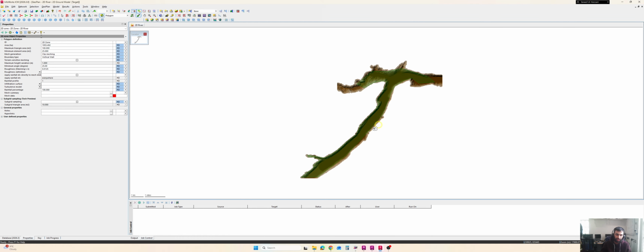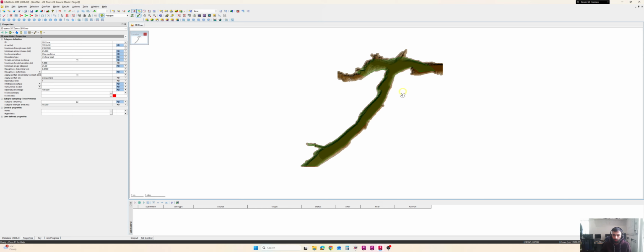This zone will be used as a mesh, and we have this properties panel right on the left. I'm going to change this maximum triangle area to something like 2300, just above the area of the polygon, as this will be used in our mesh, and change the Manning's N roughness to 0.05. And this is the mesh data. You can see it shows as red because we haven't created the mesh yet. As I have this one polygon we have drawn, and you can see these are the walls.